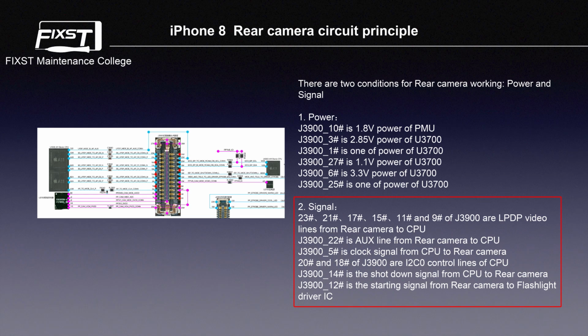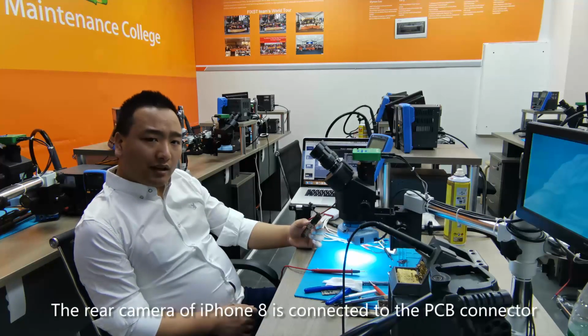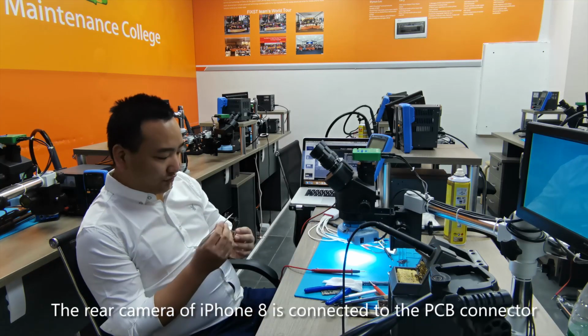Pin 5 of J3900 is the clock signal from the CPU to the rear camera. Pin 20 and Pin 18 of J3900 are I2C control lines of the CPU. Pin 14 of J3900 is the shutdown signal from the CPU to the rear camera. Pin 12 of J3900 is the starting signal from the rear camera to the flashlight driver IC. The rear camera of iPhone 8 is connected to the PCB connector.